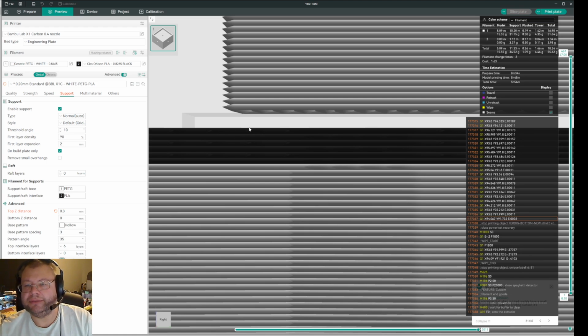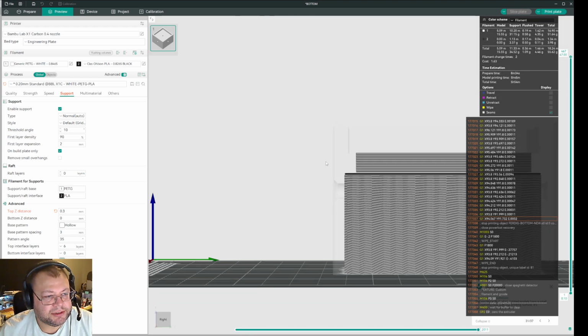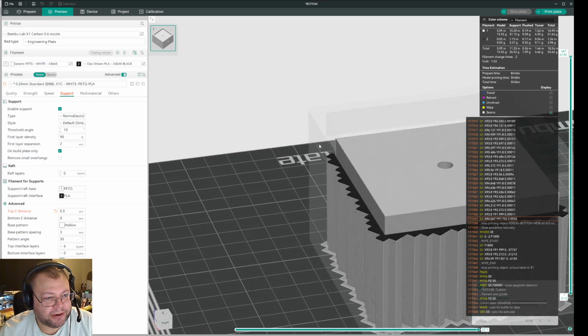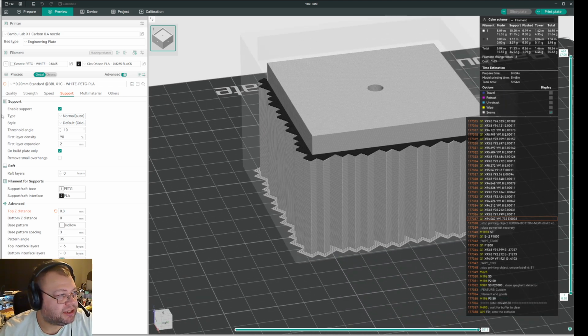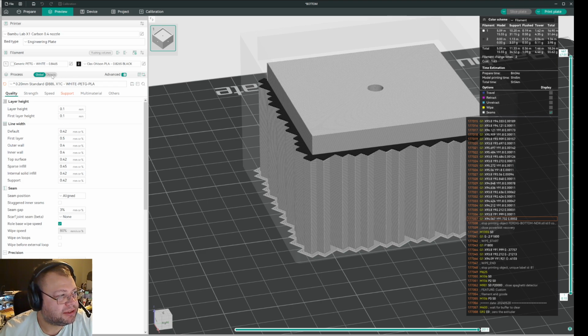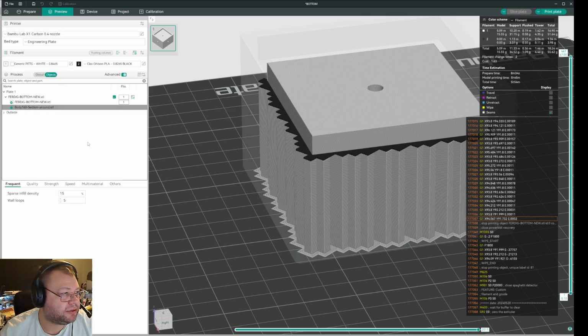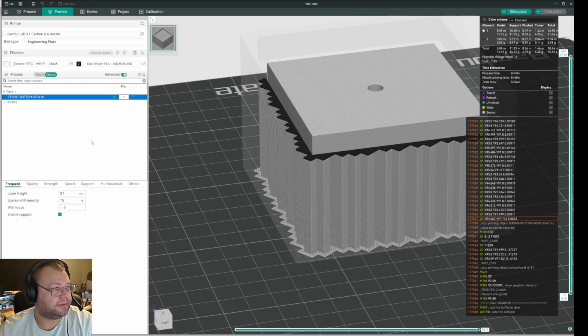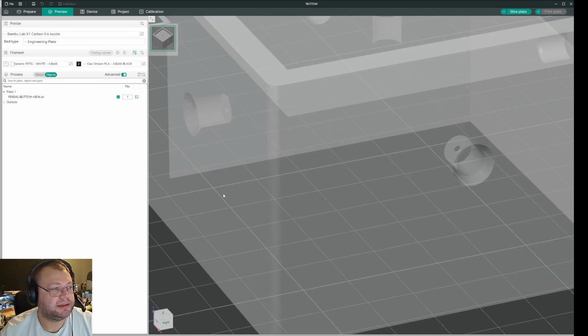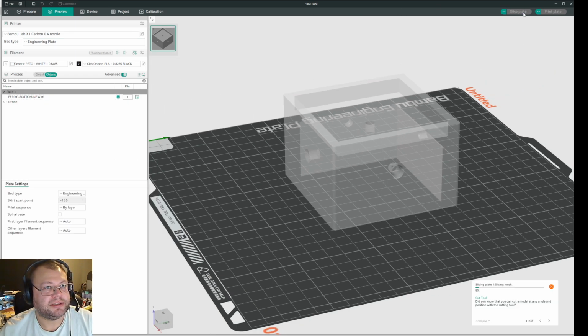So with this you can do some testing, and it is actually quite nice. I hope that was a nice way of adding section analysis to your objects. And you don't have to remove the object afterwards, you can reuse it. When you go in and set it here, you have to remove it, it doesn't let you unselect it. So just remove it, do all the settings, slice it again and you're ready to go.